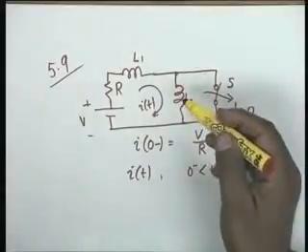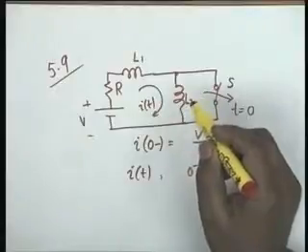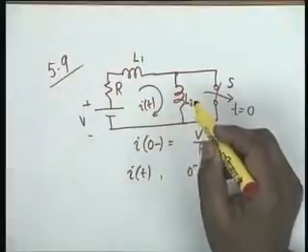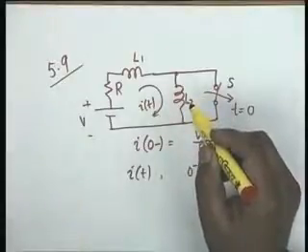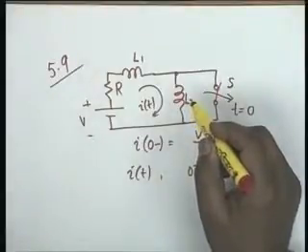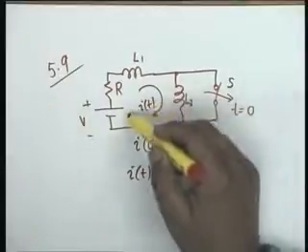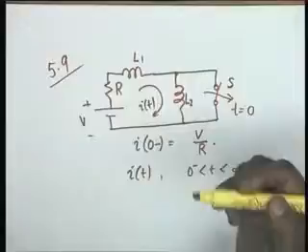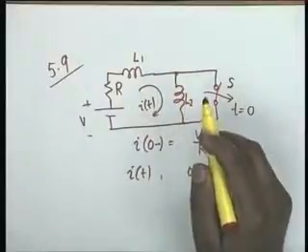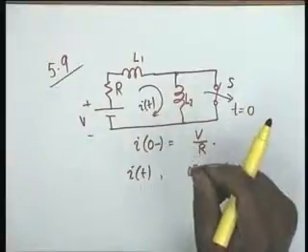This is a case in which the current in L2 has to change instantaneously in order to establish a flux, and provide a closed path for the current. Alright, this is a case of singularity, and one has to be extremely careful in solving this problem.